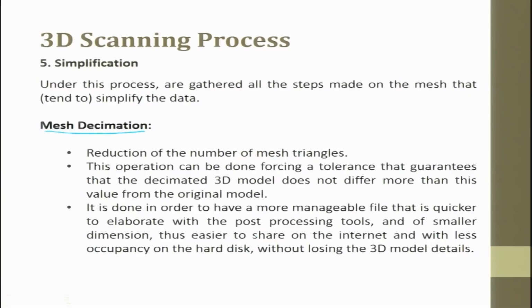Mesh decimation, reduction of the number of mesh triangles. So, the smaller the mesh, the higher will be the precision. This operation can be done forcing a tolerance that guarantees that the decimated 3D model does not differ more than this value from the original model.